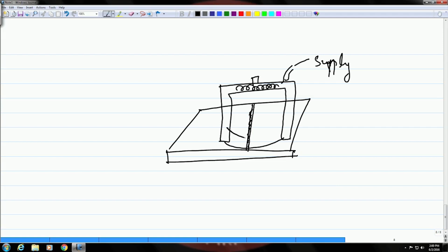Okay. So, it will be like this. This will be the field direction. So, that means in this case the best visibility will be for cracks which are oriented perpendicular to this magnetic field, which is generated by this yoke.